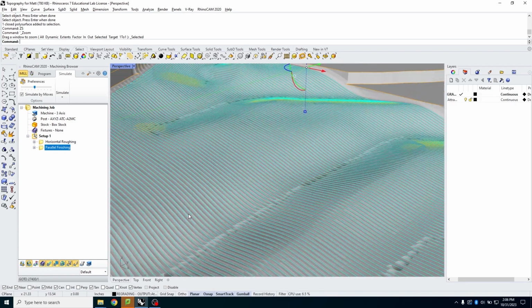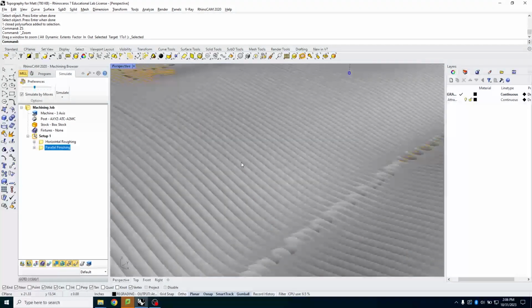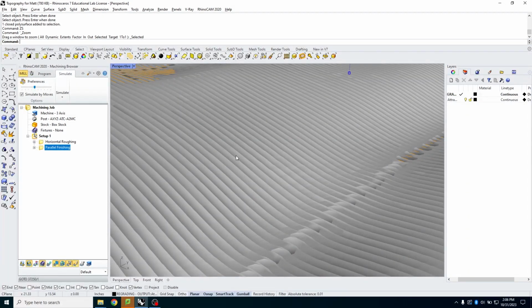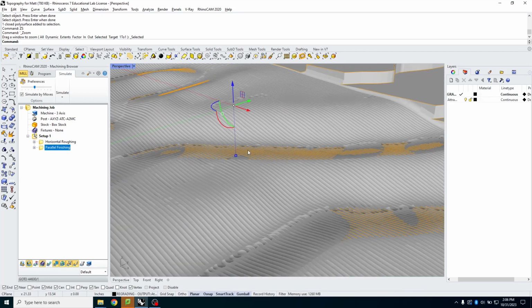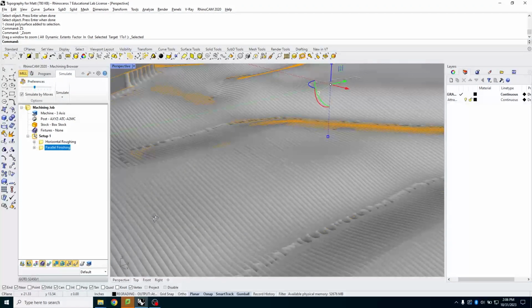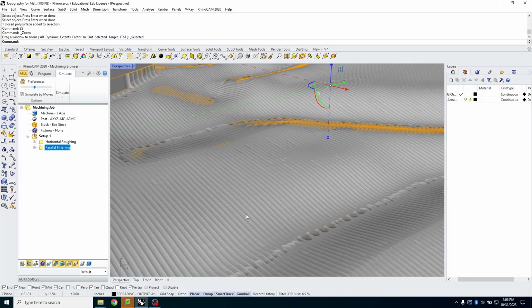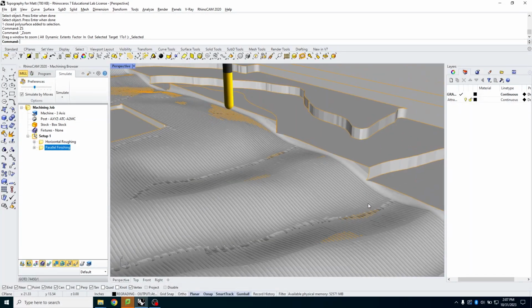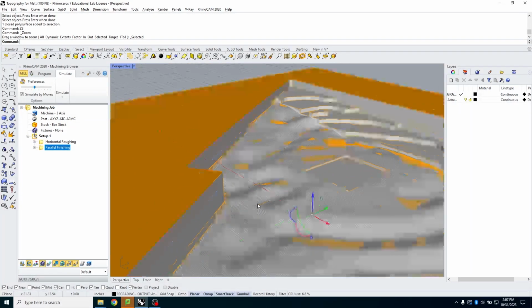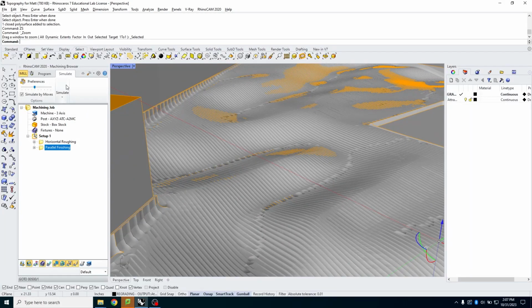But the important thing is that if I turn off these tool paths, you see these sort of gouges in the material. If you're cutting out of something like pink foam, for lack of better words a terrible material to be milling, this to me is an acceptable finish. Because in order to get this crit level finish, I'm going to need to sand, paint, sand, paint, and do a bunch of different coats over this. So if I've got something like foam, 25% step over is fine.